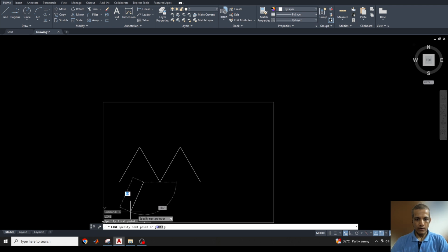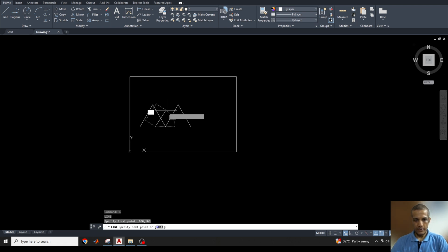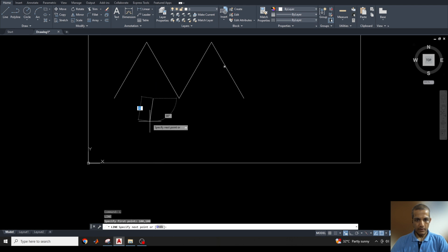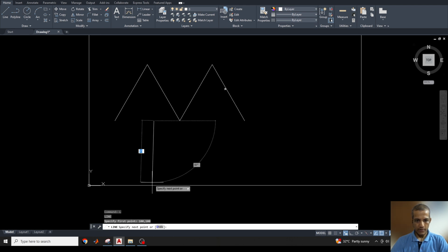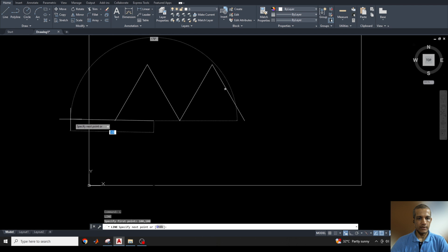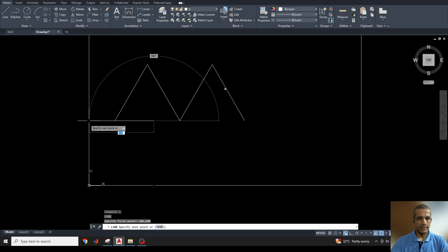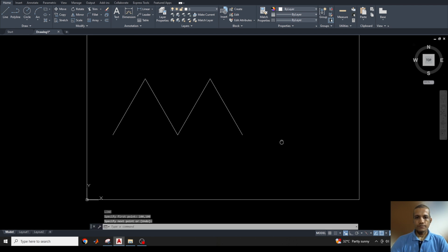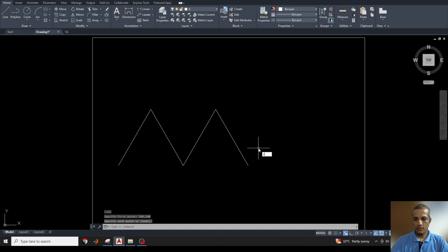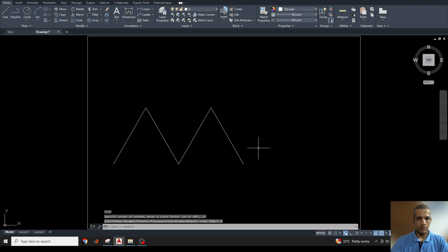And if I go down, okay, let's take it up a little bit. Now if I go down a little bit, from this point, if I come downward, you can see 100 mm distance. And this side also, if I take to the x-axis in the reverse direction, I can get again 100 to the origin. So from this origin, it will take 100 and 100. So Z enter, A enter, again to get our space.